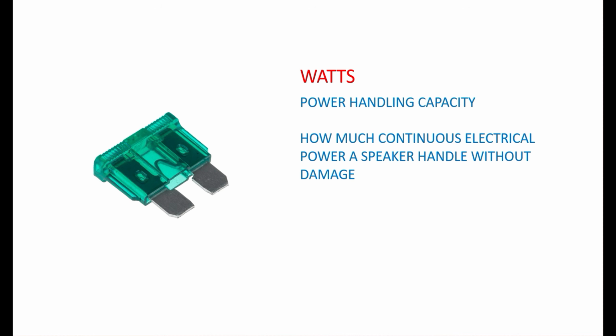The reason for that is the wattage on a speaker is not a measure of its loudness; it's a measure of its power handling capacity. So yes, a 500 watt speaker will handle more power than a 350 watt speaker. In fact, wattage on a speaker is how much continuous electrical power the speaker can handle without being damaged.